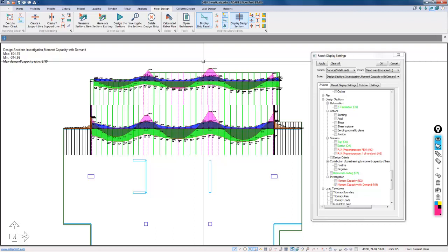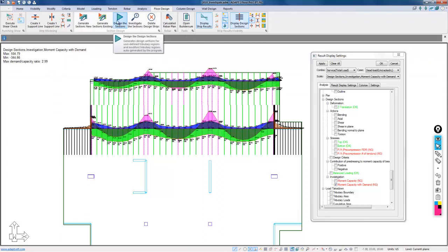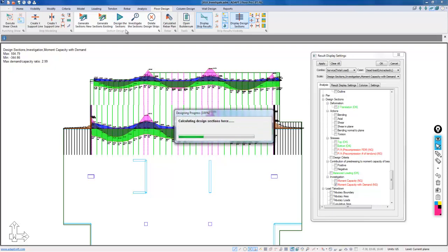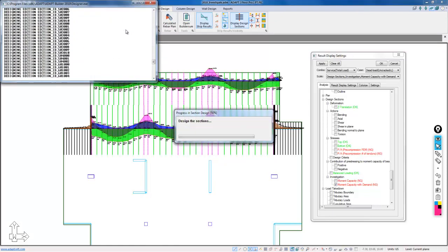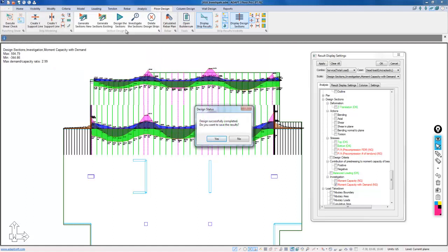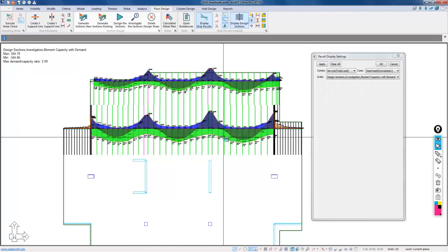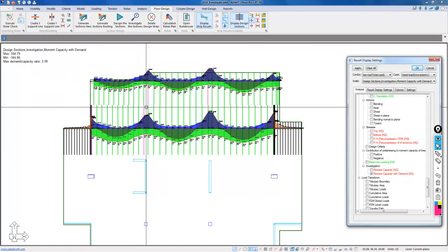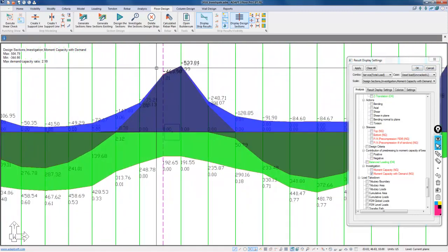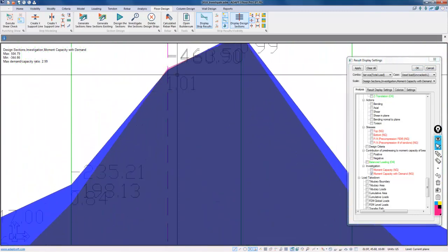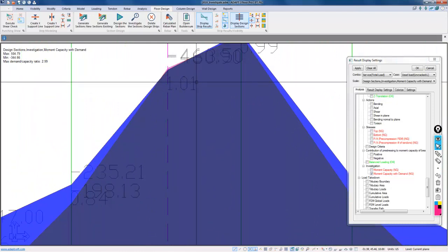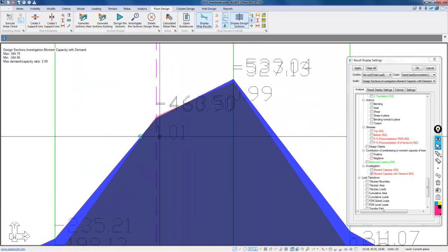Now, in order for us to check stresses in the slab, the program is currently hard-coded to check stresses only when we design. So we have to run this again using the design option to check stress. We're not going to really focus on the demand capacity, because by doing this, the program also adds rebar to meet capacity. And if I select yes, and I look at these diagrams, you can see a lot of that pink went away. In fact, the only pink options that are shown are areas where the designer didn't converge exactly below 1.001, let's say.